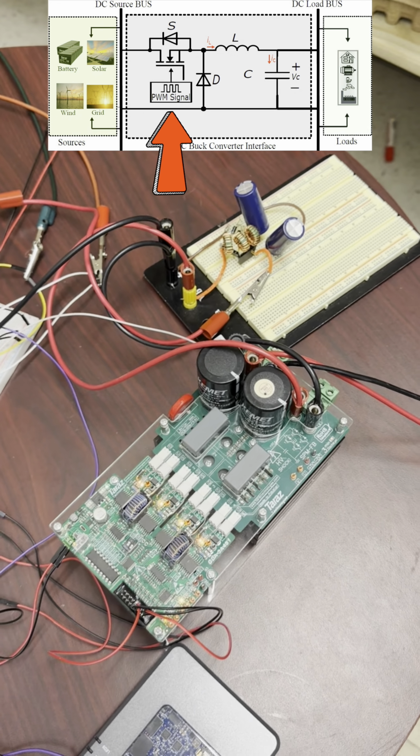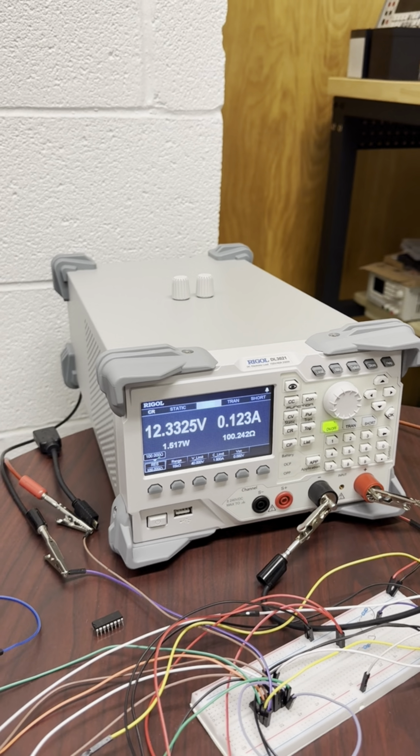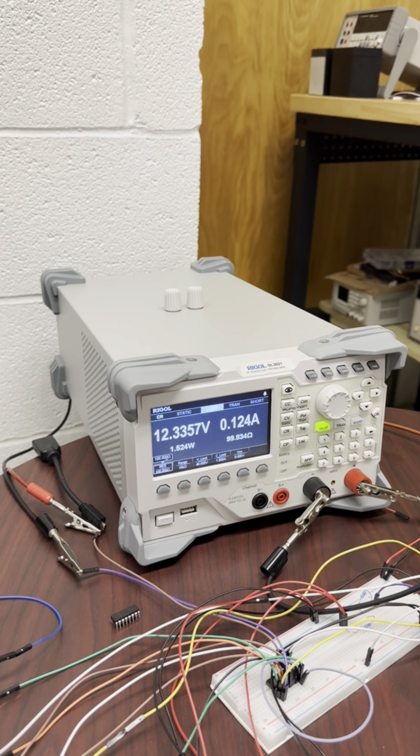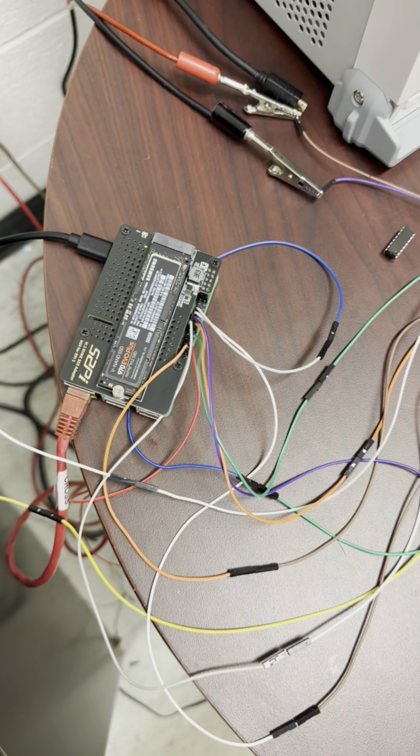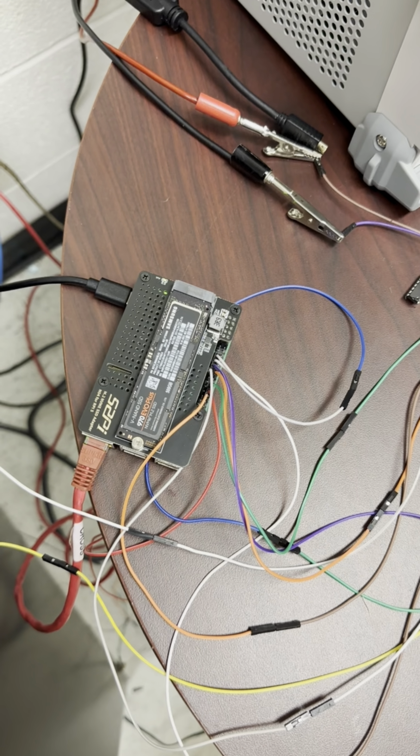For the load, I use a programmable load, which provides flexibility and safety by allowing me to set limits and replicate different scenarios. I mean, you can program it to act as an EV battery, a CPL, constant power load, or other applications. Additionally, this load has built-in data measurement, so I don't need separate devices to track data like voltage and current. Now let's take a look at the control circuitry.